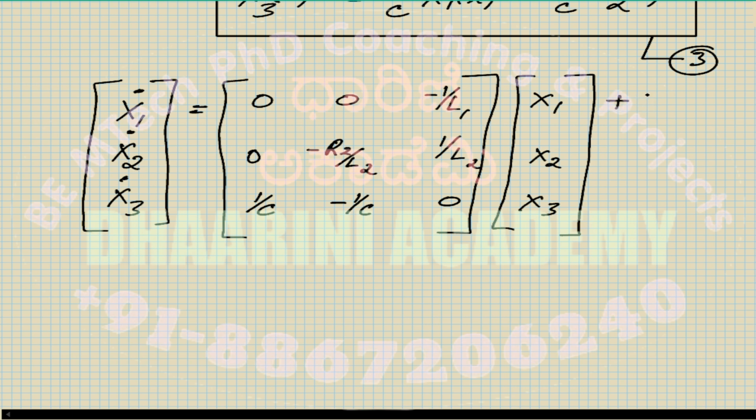So the state variables are considered. I have to look at the inputs as well, right? So only the first equation considers u of t in this thing, right? So this is 1 by L1, I guess. Then others are not considering u. So into u of t. So this is the equation that corresponds to the state variables. So states can be determined by using this.